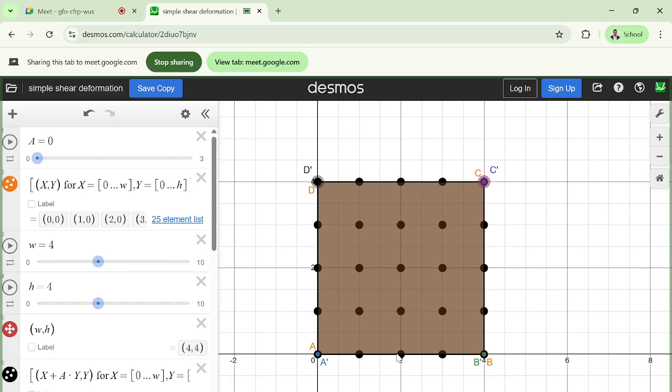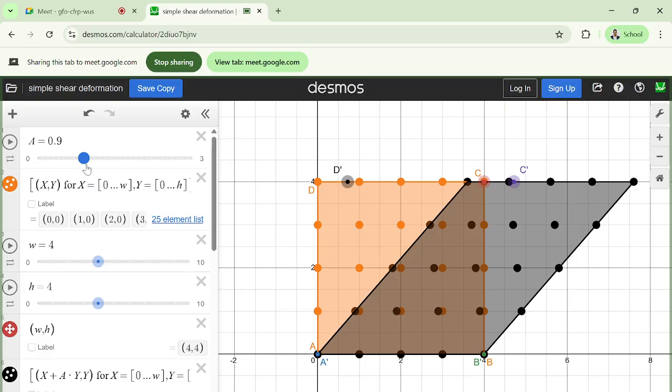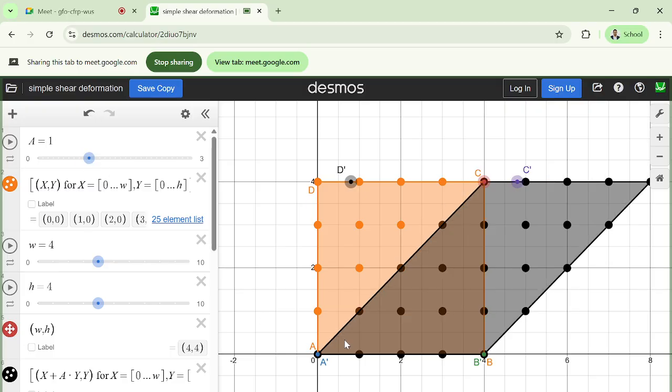And suppose I take a point here, 1 comma 1: capital X is 1, capital Y is 1. So you just substitute in the deformation field. Small x will be equal to 1 plus a into 1, which will be 2. So it will go to 2. Let's make this as 1, right? So the point initially at 1 comma 1 has now moved to 2 comma 1.